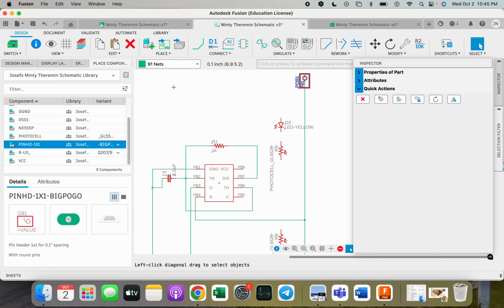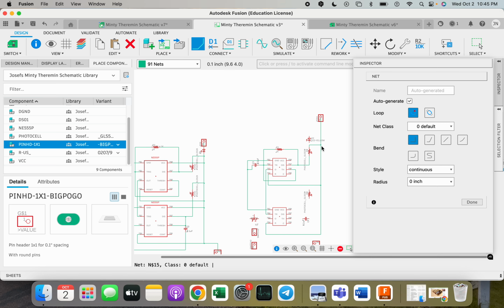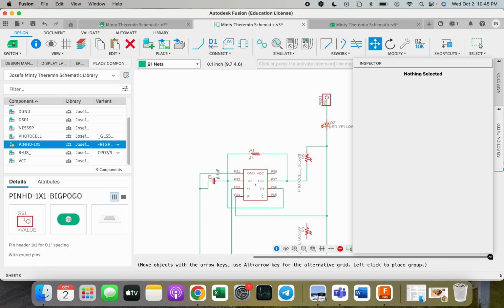So carrying on with number 7, we are coming from that join and connecting the photocell, and then taking the other side of the photocell and connecting it to our positive line. And now you'll see that that diode should be in line. If we hit escape and grab the diode and place it in here, it'll insert it into that line. If you hover over the lines above and below it, you'll notice that they've broken it. If I delete that, there's a space now, because inserting it created those connections.